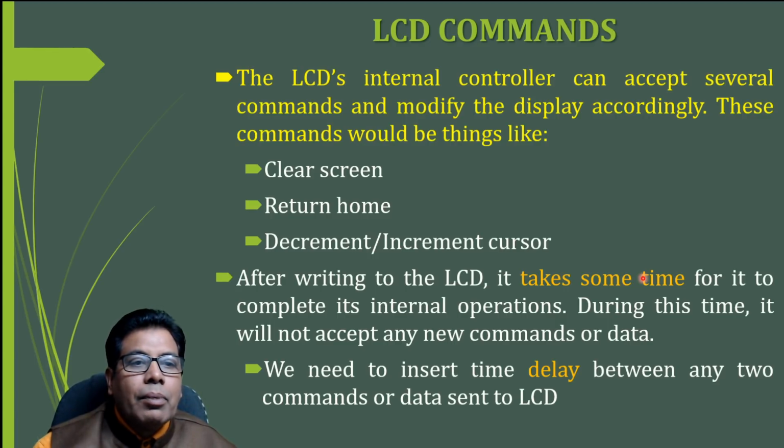These commands will say clear the screen, return home, increment or decrement the cursor, that is the position of the cursor is incremented or decremented, because generally the display will be 16 by 2 lines, or 16 by 1 line, 20 by 1 line, like that. So that's why we have to position the display accordingly. For that, different commands are there. We are going to see the details.